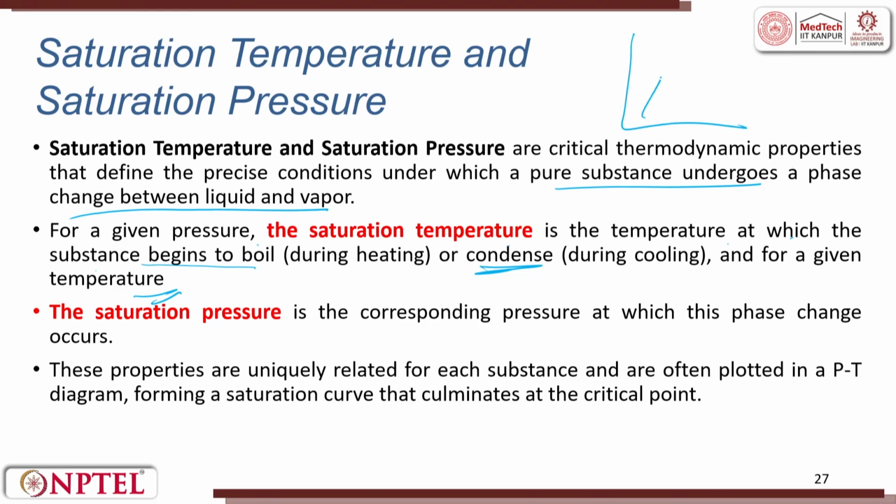So, if you go by the TS diagram, this is where the condensation starts. Boiling start, boiling end. The saturation pressure is the corresponding pressure at which the phase change occurs from liquid to gas or solid to liquid. So, these 2 points are very important: saturation temperature and saturation pressure. These properties are uniquely related for each substance and often plotted in a PT diagram, forming a saturation curve that culminates at the critical point.